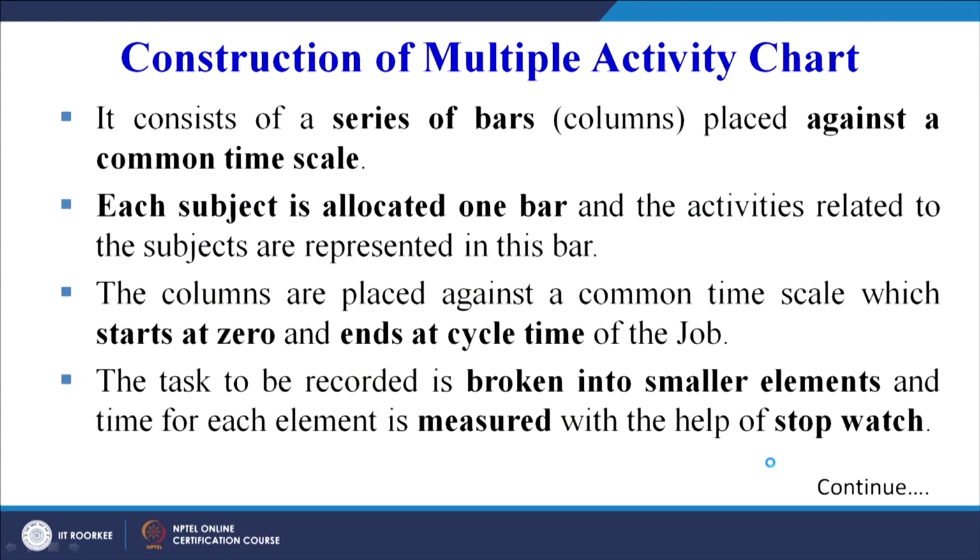The task to be recorded is broken into smaller elements, and the time for each element is measured with the help of a stopwatch. For example, I have taken the example of mold making. We are not going to focus on the procedure a person follows for making the mold, how he is ramming the sand. All that is not the object of our recording here. We are going to find out only the time taken for mold making, which we will measure with the help of a stopwatch.